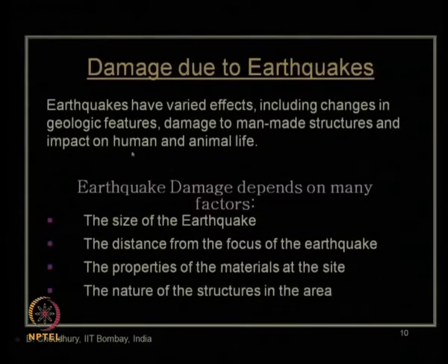Then we discussed what are the various factors on which the earthquake damage to a particular structure depends. It depends on 4 major factors. First, the size of the earthquake. As we know, as the size of earthquake increases, chances of damage will increase. Second, the distance from the focus of the earthquake to the concerned structure or the site of interest. So, if the distance increases, then the chance of earthquake damage will reduce.